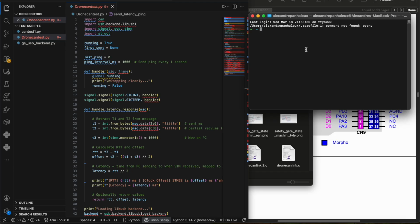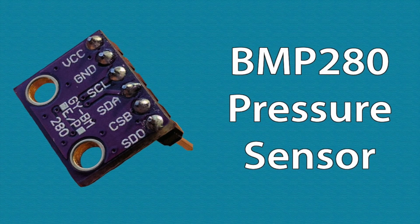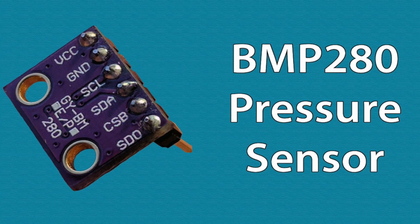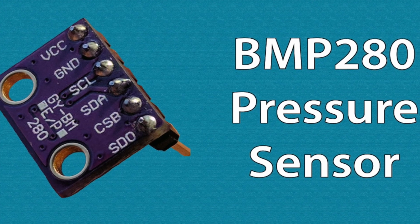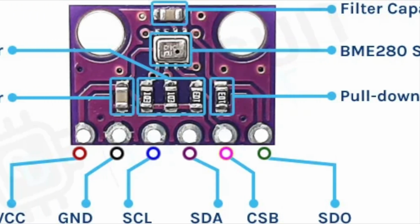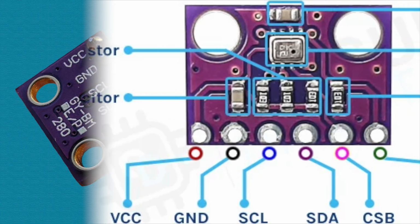So just to make a little bit of sense out of it, in the drone industry, we use a lot of sensors like this simple BMP280 to measure all kinds of data that the flight controller will need to determine its position, speed, altitude. So this BMP280 is wired over I2C. It's a two-wire synchronous serial bus. So there is one line for data and one line for clock.